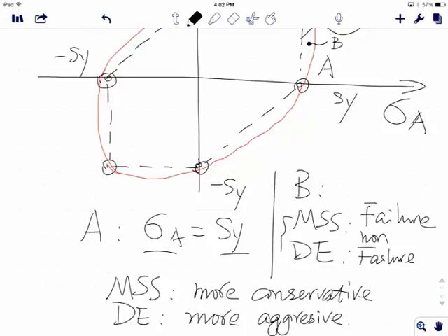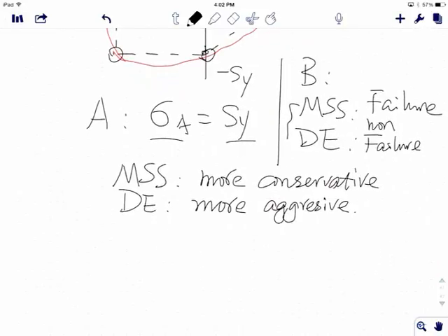That's pretty much it. So you just decide which one to use, and to put it simply, most of the time we'll be using distortion energy, because von Mises stress is a very powerful quantity we can use. One, it's easy to get. That's what the finite element gives us, right? Second, we have this criteria here, which is fully based on von Mises stress. You just compare that von Mises stress with the yield strength, and that's your criteria, right?